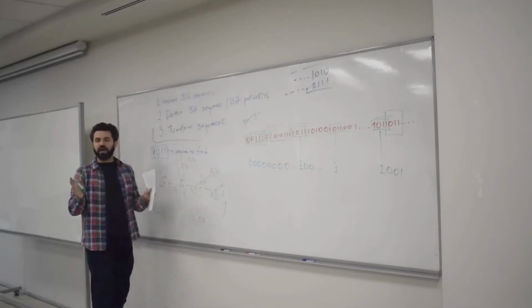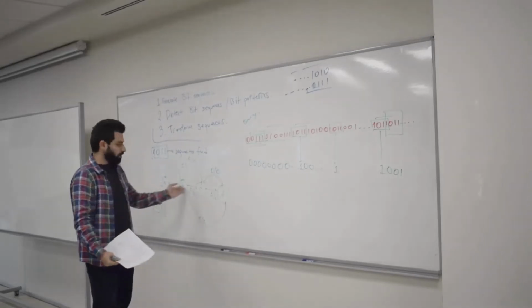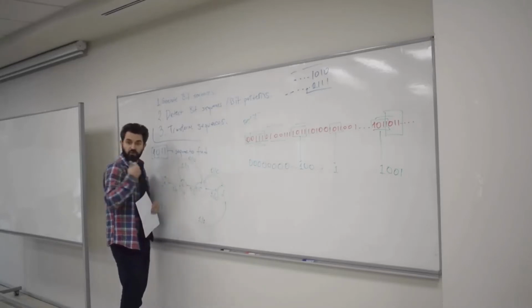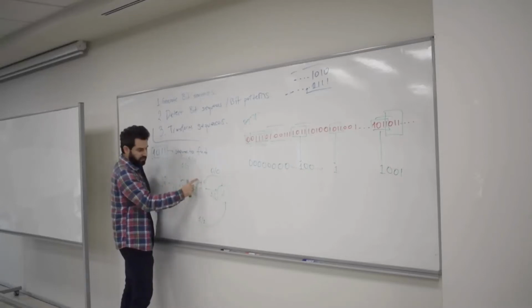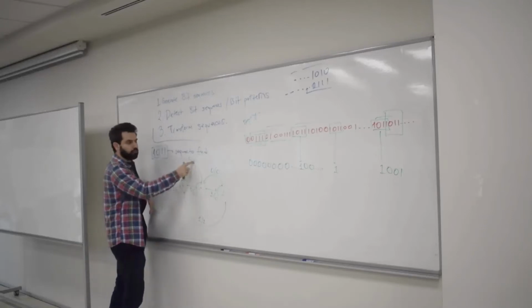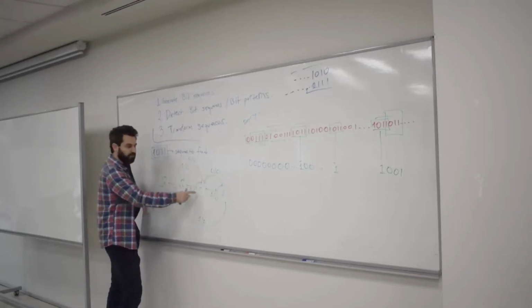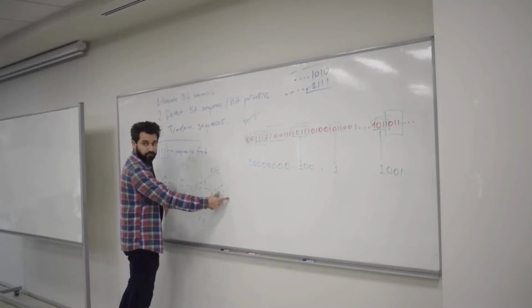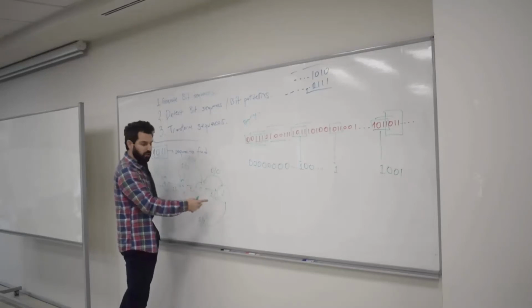At a given time when this circuit is operational, the circuit is in one of those states. If it is in C, for example, and you accept a single bit of input, if that input is 0, this state diagram says that you have to move back to A and output a 0, and your next state is A. If the input is 1, then this state diagram says that you have to move to D. Your state transitions to D, and you have to output a 0.